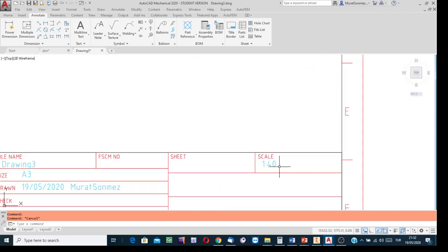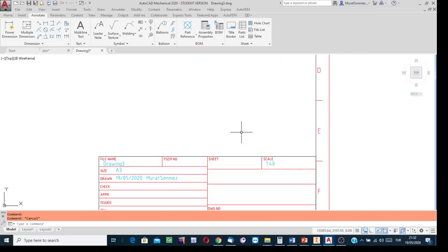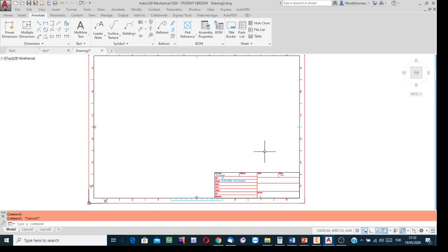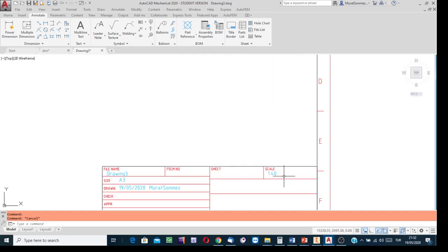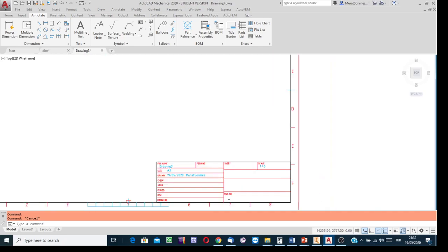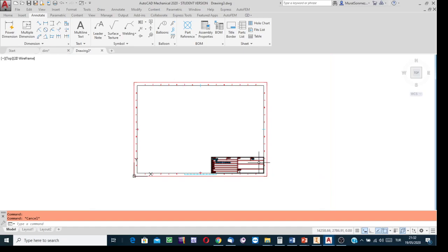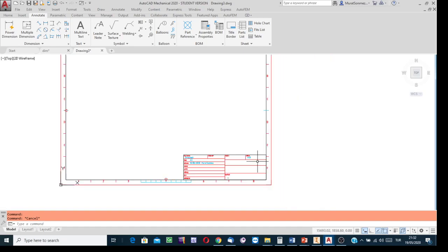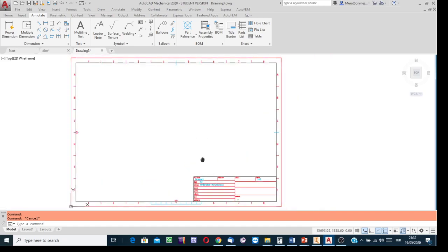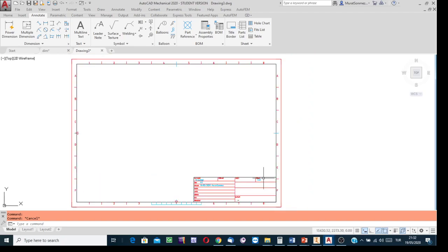Well, the scale factor, for instance, 1 to 40. Whatever you write as the size of the entity feature of the object, that size value will be multiplied by the scale factor, and it is going to be created 40 times smaller. At the dimension indication stage, if you have such a template, AutoCAD knows that it should diminish the projection 40 times.